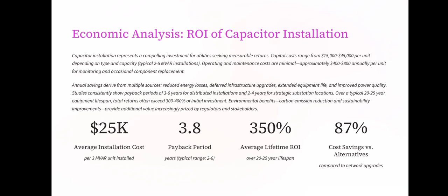Economic analysis: ROI of capacitor installation. Capacitor installation represents a capital investment with compelling returns. Capital cost ranges from 15,000 to 45,000 per unit depending on type of capacitor. Operating and maintenance costs are minimal, approximately 400 to 800 annually per unit for monitoring and component replacement. 25K average installation cost per 3 MVAR unit installed.